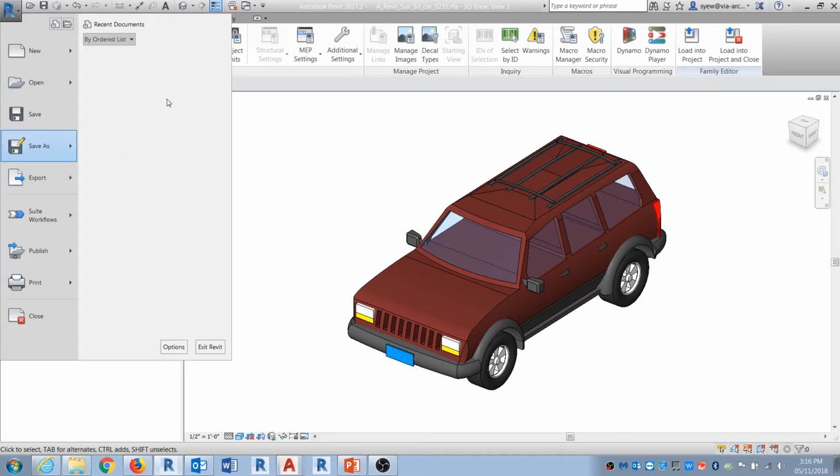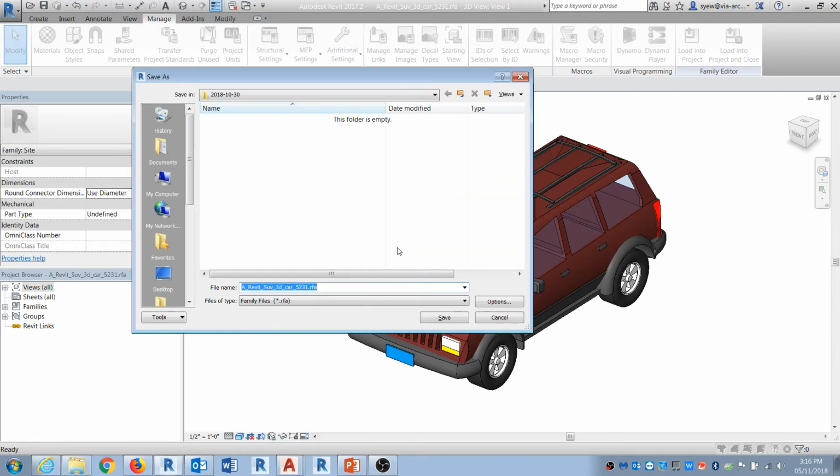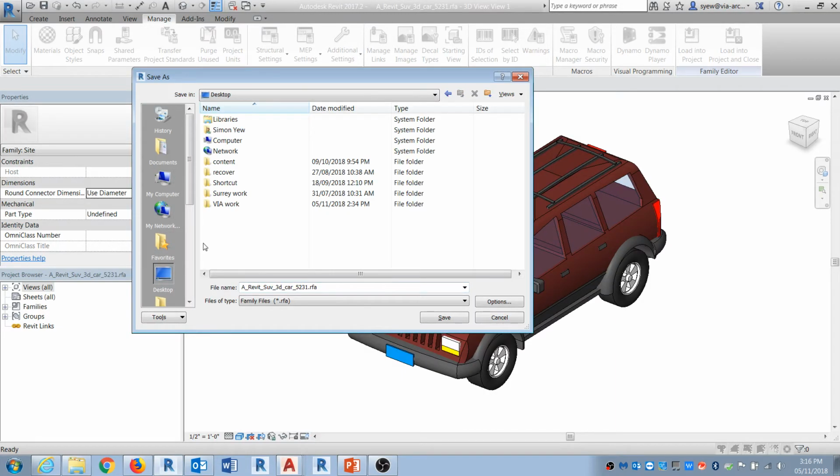Yeah, that's the danger of having shared. Sometimes shared can be very infectious. So what happened with Revit shared is that, assuming that you want to tag that element, and if that family is put inside a nested family, it treats it like it's a shared object so that you can actually tag it. But in this particular case, you do not want to have that, or else it will not scale properly.